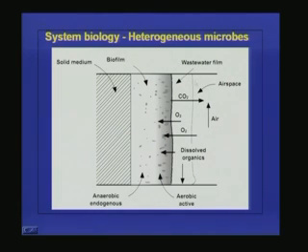So how do the reactions take place in the biotrickling filter? The term itself does not give the actual picture of the treatment system. Though we call it a biotrickling filter, the filtration part is very negligible. The treatment occurs because of biological action. The waste present in the water will penetrate into the liquid film. From there it will come to the biological film, and biological action will take place, and as a result the organic material will be converted into carbon dioxide and water.